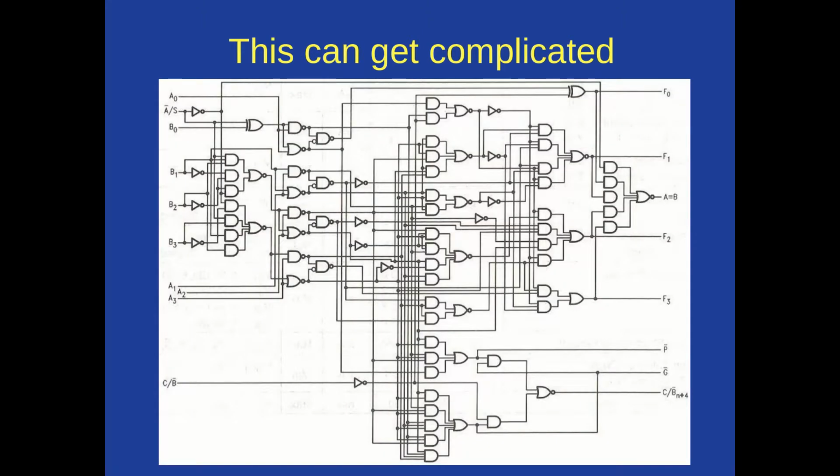So here's a 4-bit adder. It's got 2 4-bit numbers, A and B, so this can add numbers from 0 through 15, and a 5-bit output. And there's a lot of gates in here. So in our Verilog file, we have to describe each of these gates, and we have to say, okay, I want this input on this gate to come from the output of this gate over here. And it's almost as error-prone as actually building it up with wires on a proto board. This would be a nightmare to code. The only difference is you're typing lines of code and editing and checking instead of staring at wires on a physical board. Not an ideal approach.